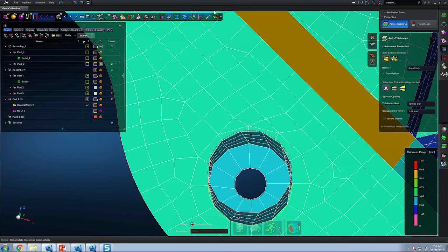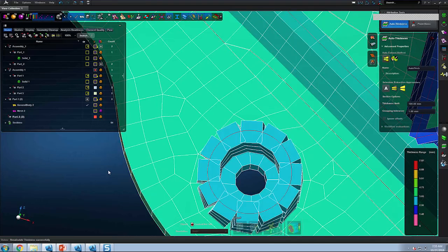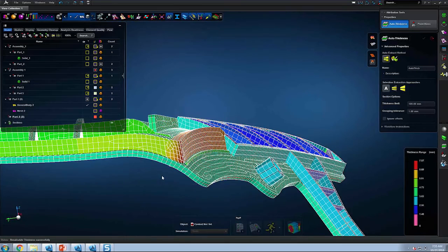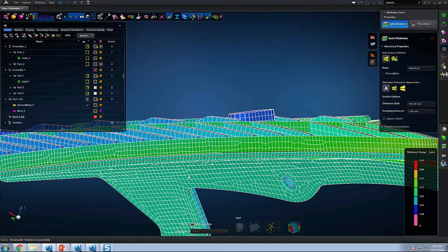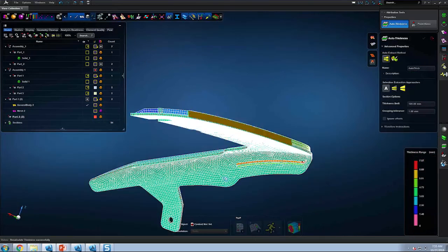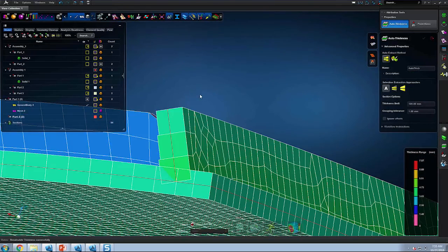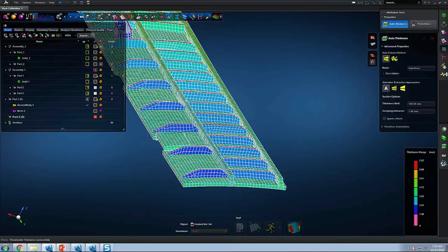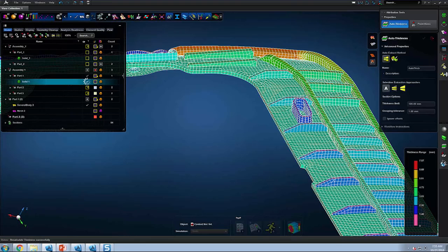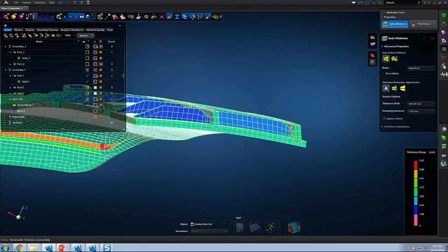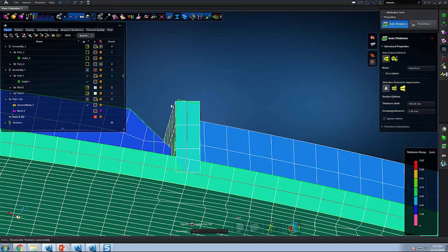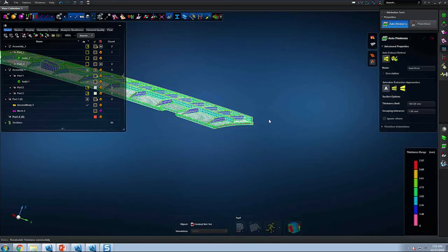And here, if I display what the thickness properties look like in 3D form, we see a number of things. Number one, we see changes in the thickness distribution, and this is really indicating that the thickness properties are in fact changing through the thickness or the depth of the ribs. If I superimpose the solid, I see that the application has in fact done an excellent job of creating thickness properties for these drafted sections of the model.